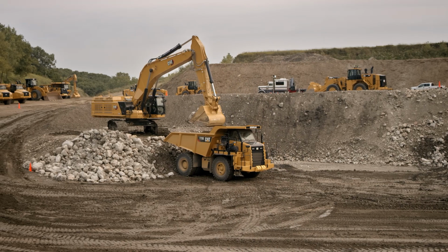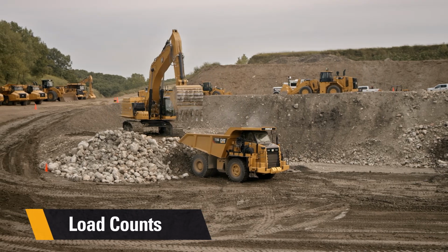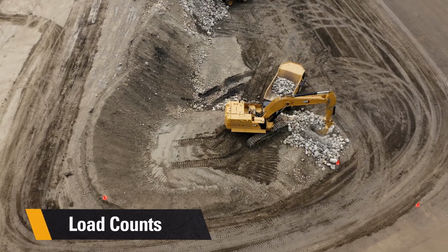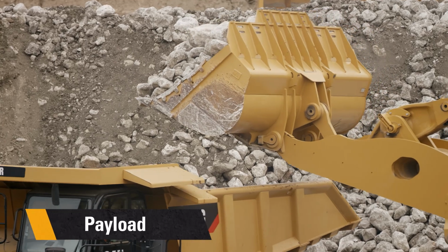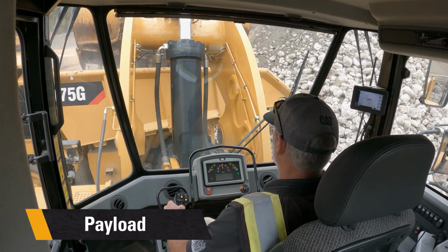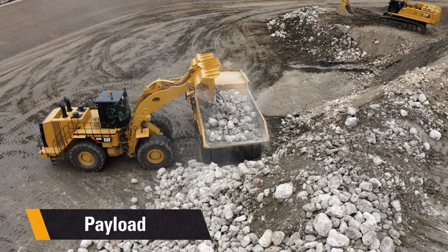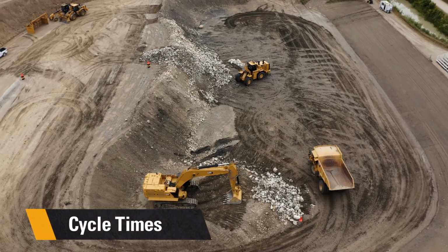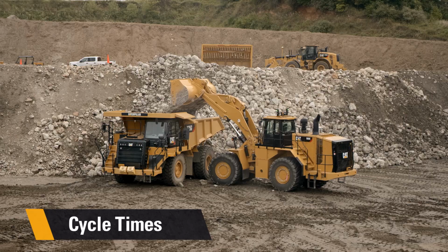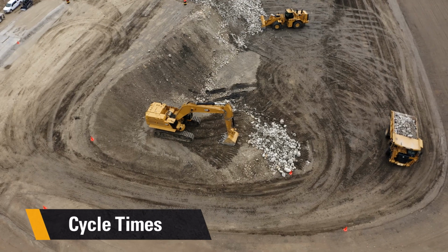So let's start by talking about some of the features of CAT productivity and what it's going to give customers. A few of the key heavy hitters are: one, load counts. How many loads did that machine perform throughout the day? Where do they come from and where do they go? Next one is payload. If that machine is equipped and able to send us that payload detail, we can show the user how much material that machine moved and again where it came from and where it went. The third is going to be cycle times. How long it took that machine to run from point A to point B and back to point A again, so that user can understand the productivity of that machine.